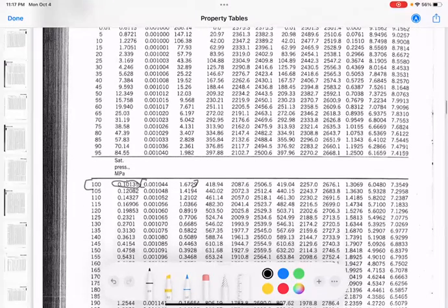Okay, so again, we go to the 120 entry. We make sure still with the same specific volume, like I said, it's rigid fixed mass, so the specific volume does not change. Sorry, I circled the wrong one, this is the pressure. These are the specific volumes, and we see that we're within the range of 0.001060 and 0.8919.